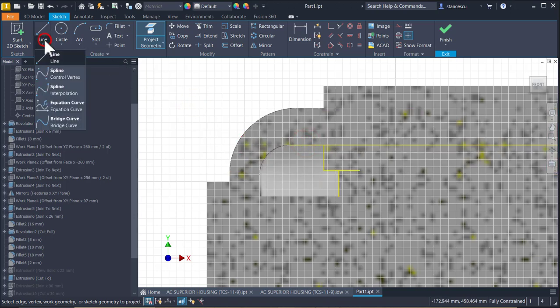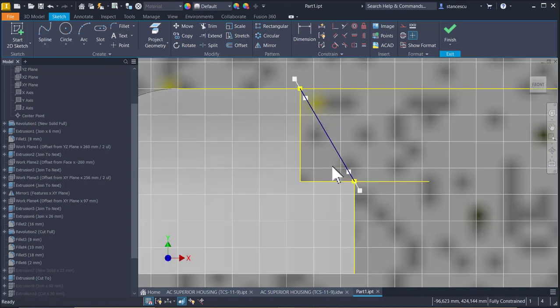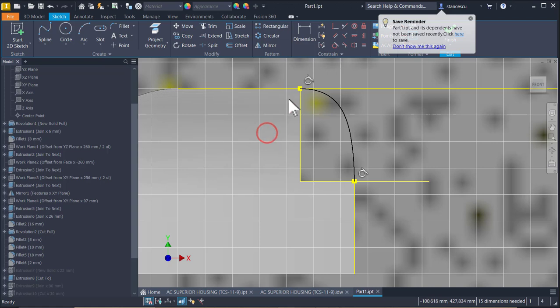We use not line but spline interpolation between these 2 points. OK, and now you see this ends of a tangent, so you can place it horizontal to be tangent with this line. The other is so, again tangent. Now we have here a closed contour,